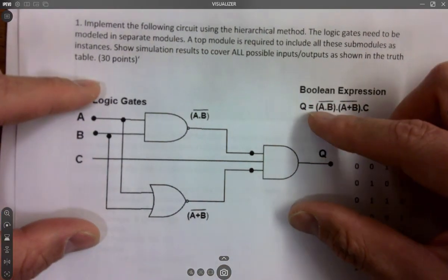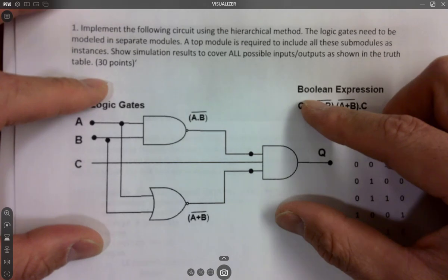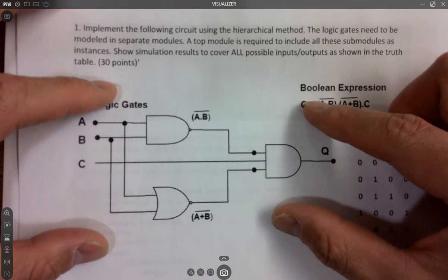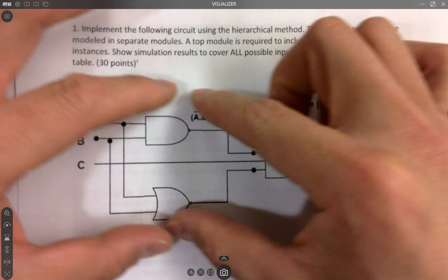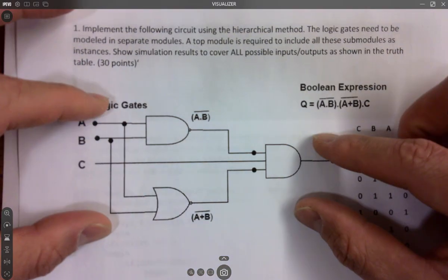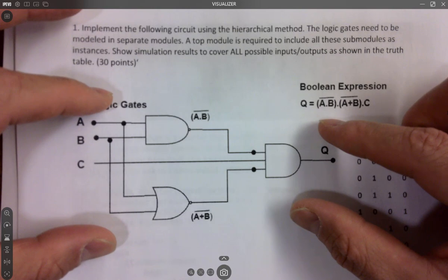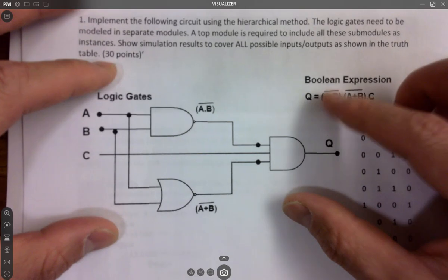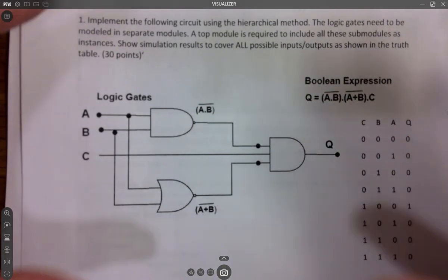And that top is a system top. It's not a simulation top. Don't get confused. The top is still a module. The simulation top is one thing, but the top for these three things, the three gates, is a chip. You don't need any simulation files, stimuli, or signals in it. It's just the top module. It's simply just a chip.